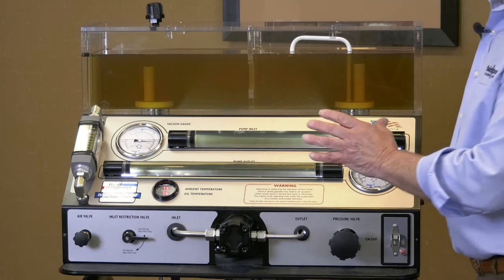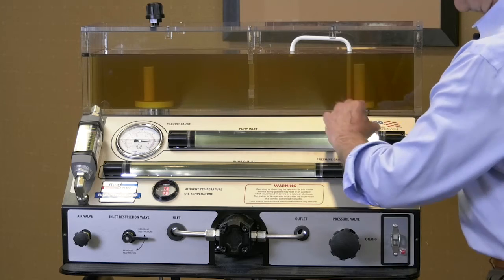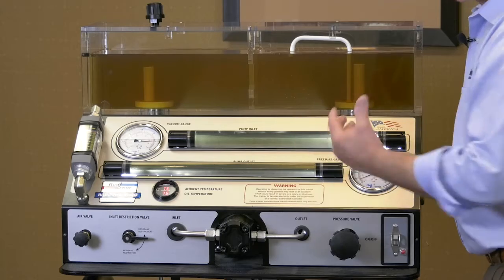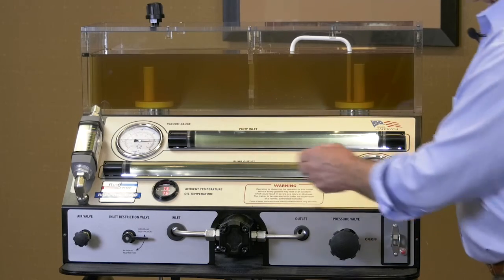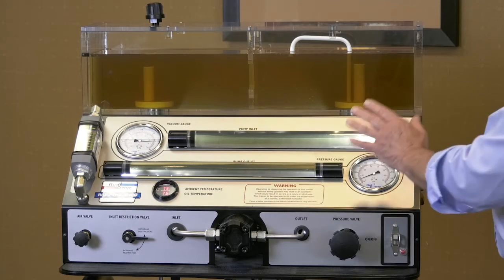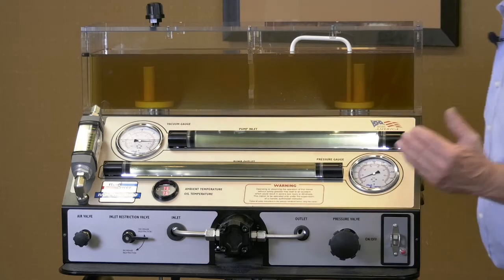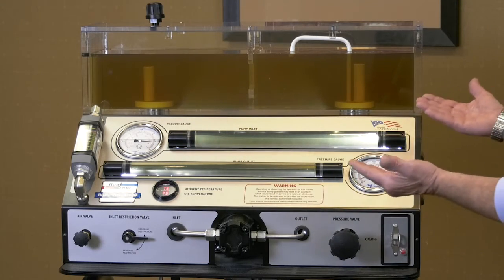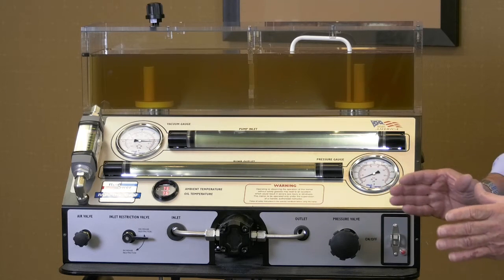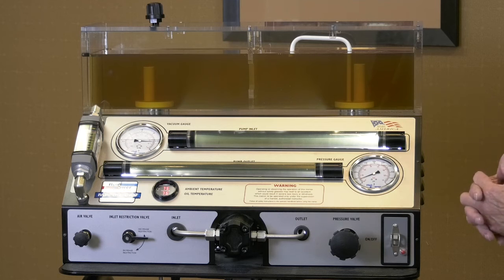As you can see here, there is absolutely no turbulence in the intake. We've got what we call a laminar flow. I have no turbulence whatsoever in the discharge line, and there is no evidence that oil is even flowing in the reservoir. No evidence whatsoever. This is a perfect situation for a hydraulic system.